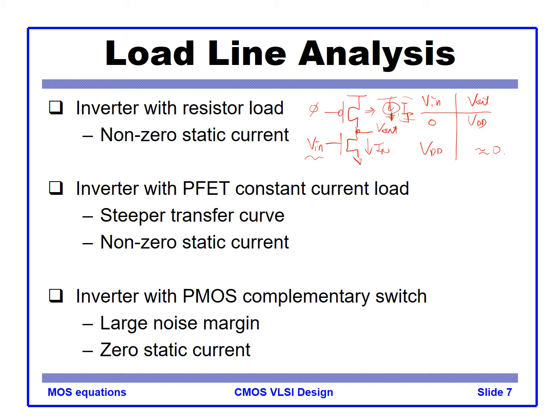Initially, IN will be greater than IP, but once the output gets close to 0, the NMOS will go into the triode region, and the current IN will collapse until IP and IN equalize, right?